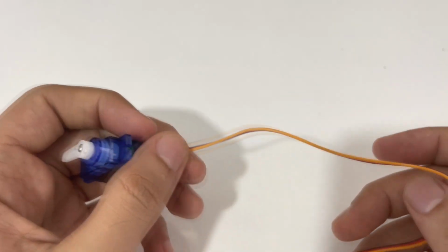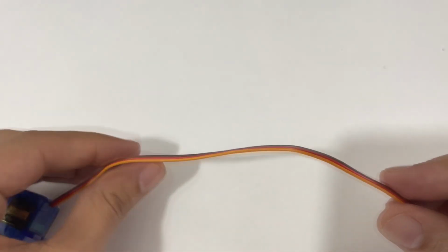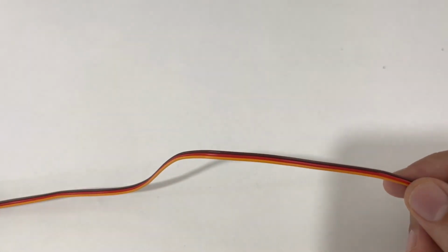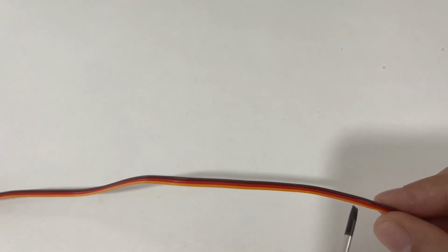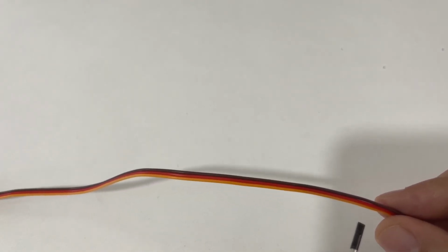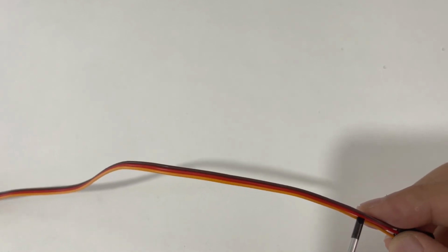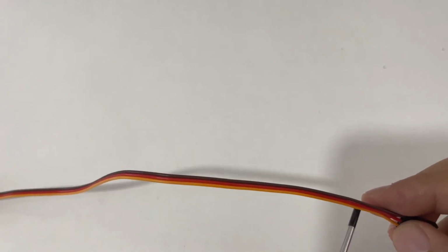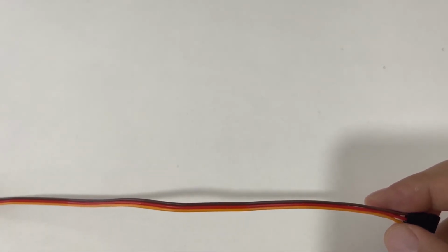Alright, we generally have three different lines in our servo motor. You see, the brown line is the ground line. So here is our ground line. And also the red is the 5 volt line. So here, this is the middle line. And also the orange is our signal line. Together with Arduino, we can control our servo motor angularly.